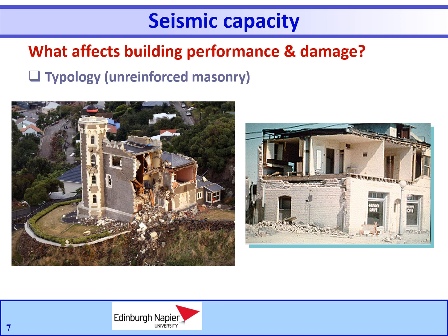To achieve ductile behavior in masonry, it is necessary that the shear strength of the wall be greater than the tensile strength of the reinforcement, so that the wall does not fail in shear first, and to ensure a kind of bending failure by yielding of reinforcement.